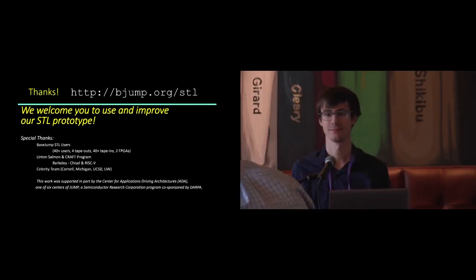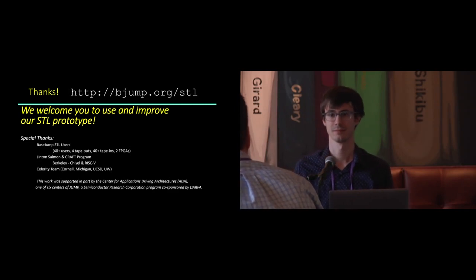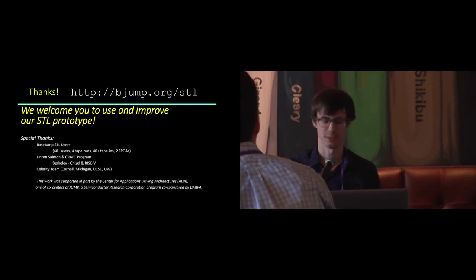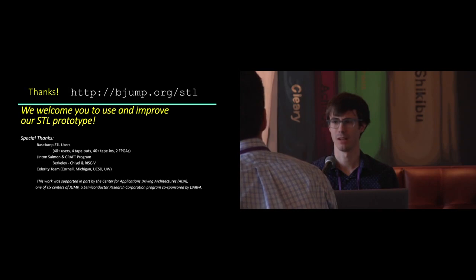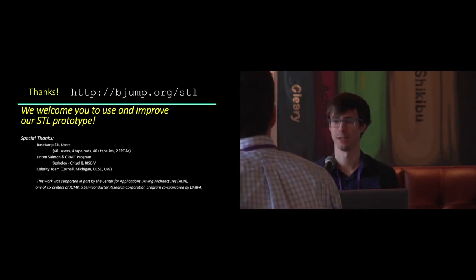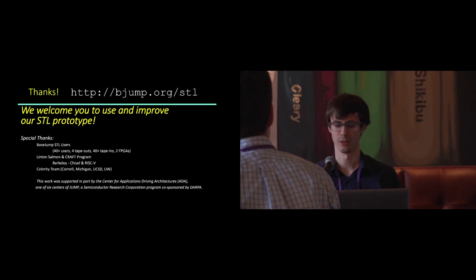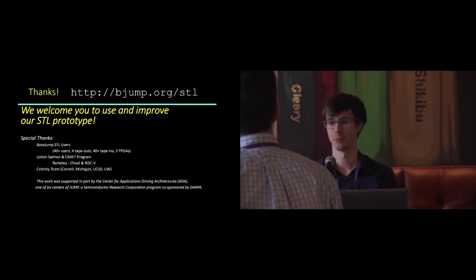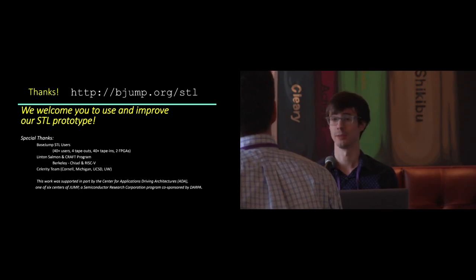Hi, do you support any standard buses like Wishbone or AXI? We have chips that support AXI. I want to say some of the support for AXI is committed to BaseJump. Wishbone, I don't think we have any chips that support. Usually our model for how we add things to BaseJump is what we've used in our chips. We test, battle harden, and then contribute it back. So we'd be incredibly open to receiving contributions like that.